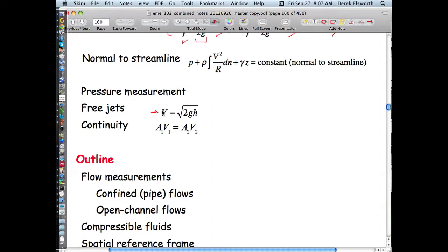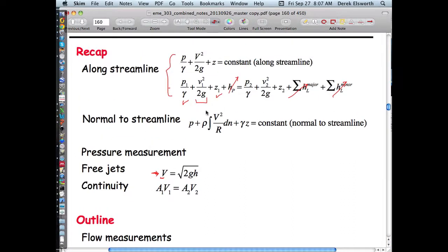And so that's why we can think of water as a bucket full of balls, of which the balls are falling out, and this is exactly the same velocity as if we dropped a ball from this height starting at velocity 0. By the time it's h below my hand, the velocity it'll be traveling at is this particular velocity. Nothing more than that. And the other thing that we talked about was that sometimes if we're trying to solve Bernoulli's expression, we have 6 quantities, and if we have only one unknown, we can solve for the remaining unknown.